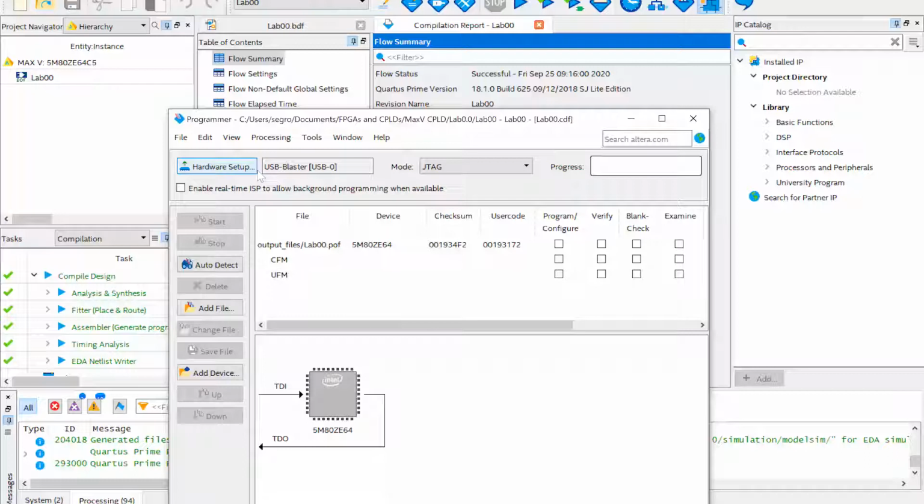They're from Intel. One of the things that came up just a couple of days ago was that in step 1, the instructions from Intel say to plug the USB Blaster download cable into your PCB, and the found new hardware dialog box appears. What happened yesterday was that the dialog box did not appear. If it does appear, you can just follow the instructions. But if it doesn't appear, we'll have to do it manually, which they show you how to do on page 28, but it might not work terribly well.